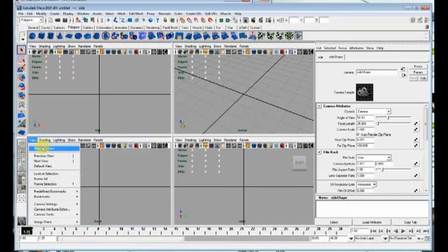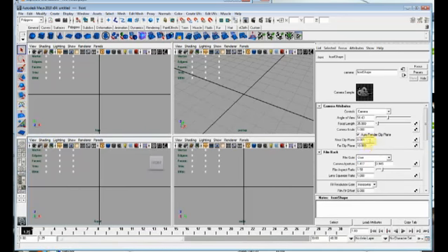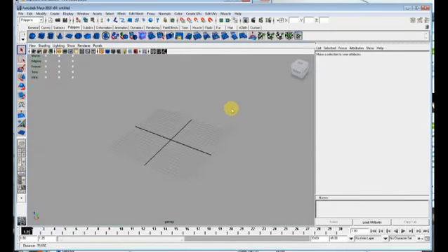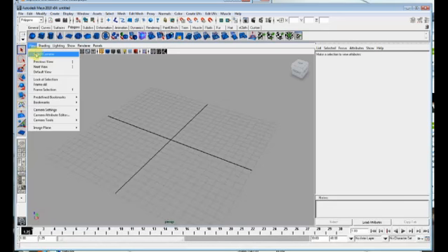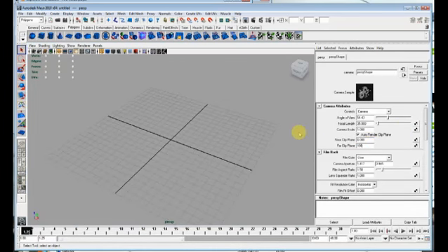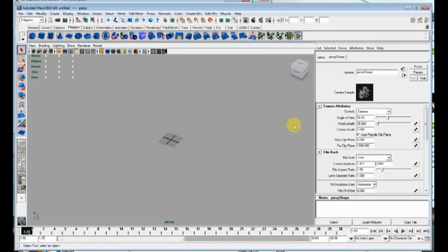And then you go to the next one, select camera, and you do 0.001 to 100, and then the last one, select camera, 0.0001, tab, 100, tab. And now when you go back, you can see your whole grid until you're about 100 meters away. Now in a lot of cases, I'll stretch this all the way out to 1 kilometer, so 1,000 meters, and tab out. And that means I can see the grid all the way out to 1 kilometer, which means I don't get lost very often.